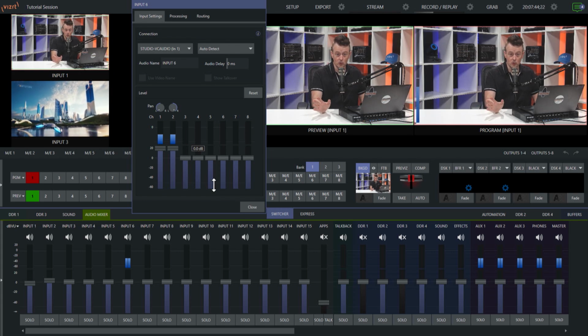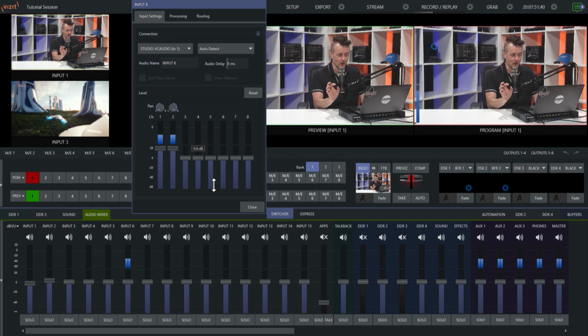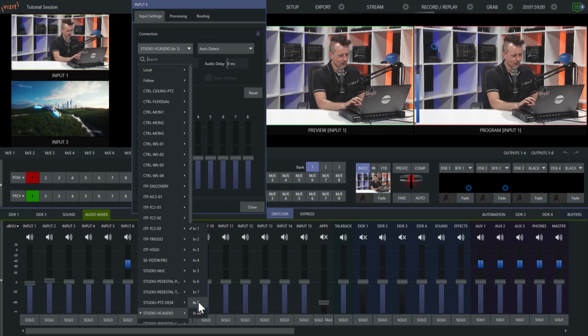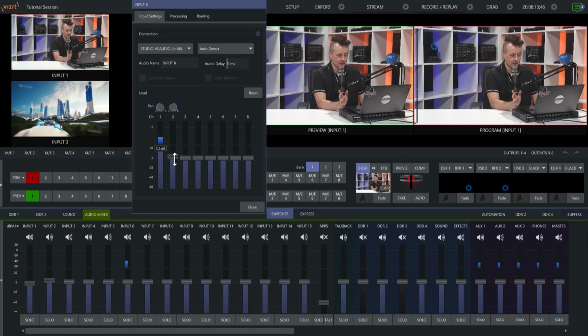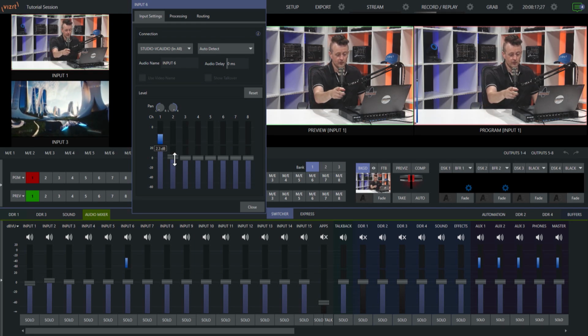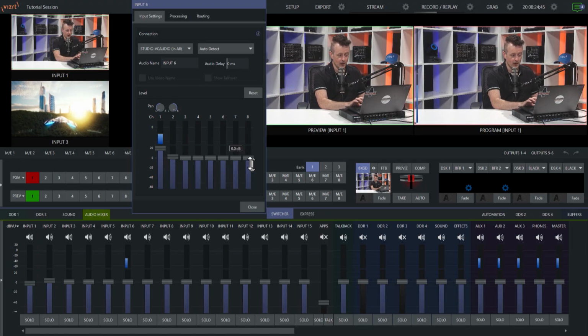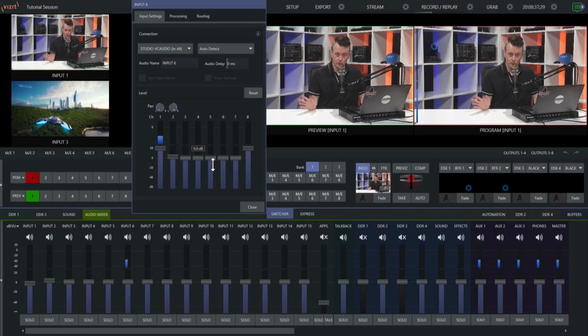But what I really want to show you here, this is where it can get really interesting. So not only can I bring in just the one source, but I can bring in all of these in a very unique way. So if I click on this drop down again, go to Studio VC Audio, you'll notice I have my inputs 1, 2, 3, 4, 5, 6, 7, 8. But then I also have the last one here, which is "All", and this is where it is interesting. So if I click on that, like so, now you'll see, let me move this out of the way, that my input is coming in on channel number 1. So if I, for example, unplugged my XLR connection from input number 1 over here into input number 8, you would see those levels bouncing over there. So that allows you to take full advantage of the 8-channel audio sources that you have available to you within the TriCaster side of things, which is pretty dang cool.